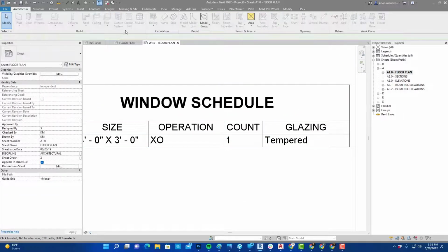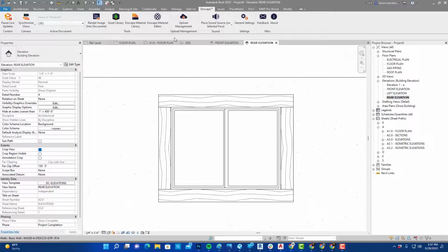So today we're going to start the window itself. In part 1 we did the window panel, which is the part with the glass in it. Today we're going to do the window frame, and that's going to be a sweep, which is swept around the window opening. And we're also going to start on the window trim itself, and I'm going to share the trick that I learned to make your material go the right direction.